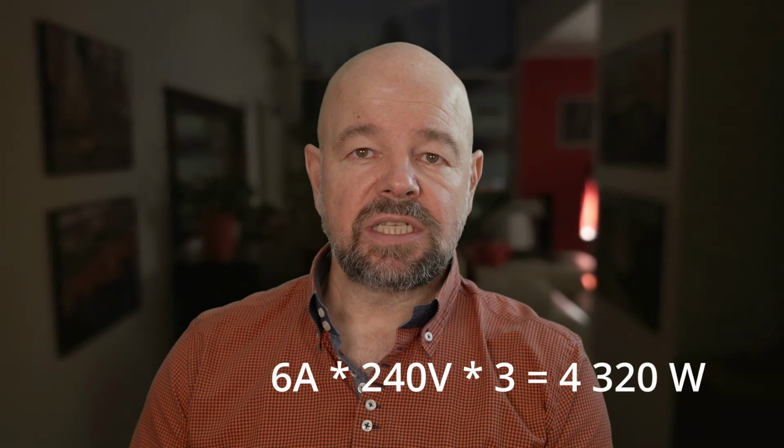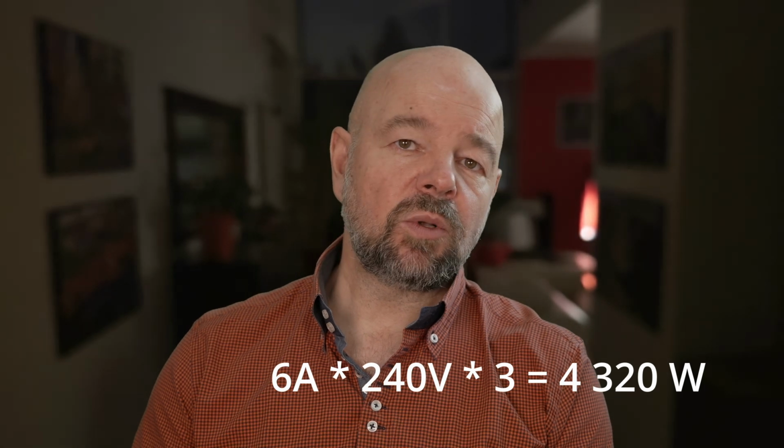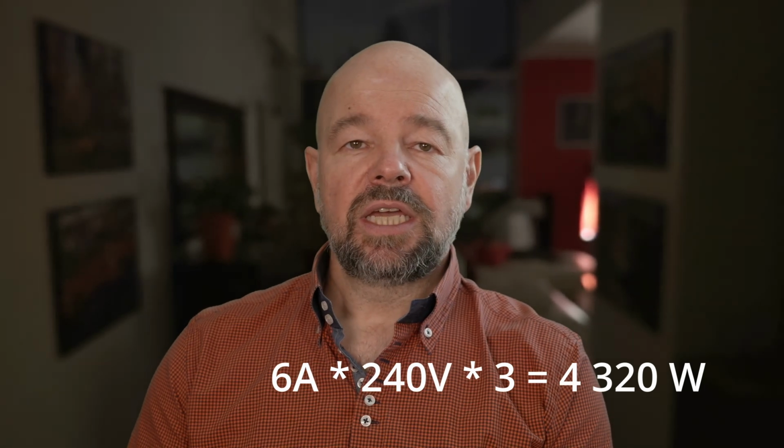So now we've established that the wallbox maximum power is limited to 11 kilowatts, which is 16 amperes times 240 volts times 3 phases. At least this is what we have in Europe. On the bottom end, it's limited by the minimum charging current, which is 6 amperes. This doesn't really depend on the wallbox or the car. This is a standard. So if the current goes below 6 amperes, the cars will just stop charging, which explains the limit that I explained earlier. On 3 phases, 6 amperes times 240 volts times 3 phases is 4.3 kilowatts. This is the minimum you can charge with a 3-phase charger.